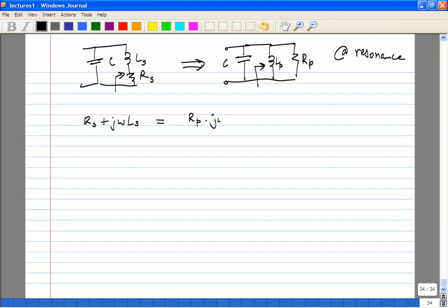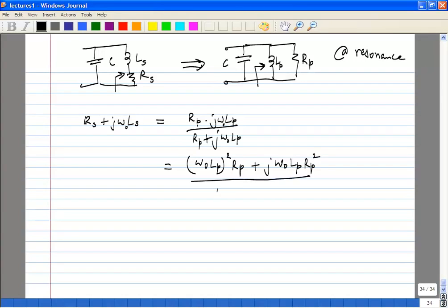So it's RP times j omega LP over RP plus j omega LP. Actually, what we'll do is we'll use omega naught because it's very close to resonance. At resonance, let's simplify this further. So you have omega naught LP whole squared times RP. You multiply the numerator and denominator by the conjugate of the denominator, right? Over...